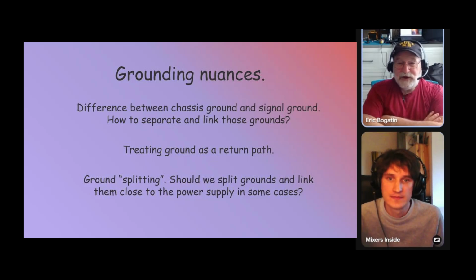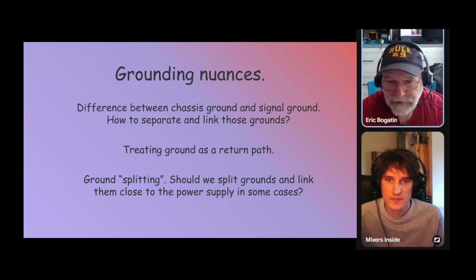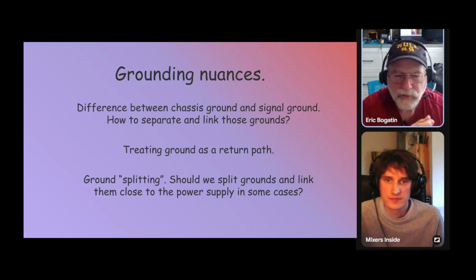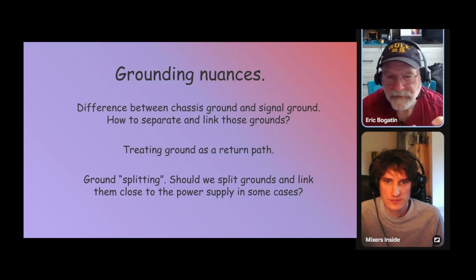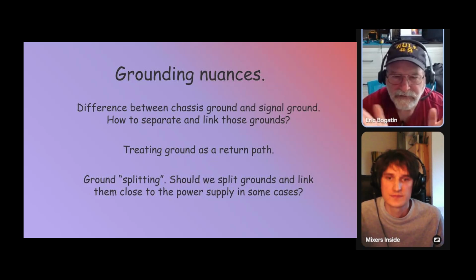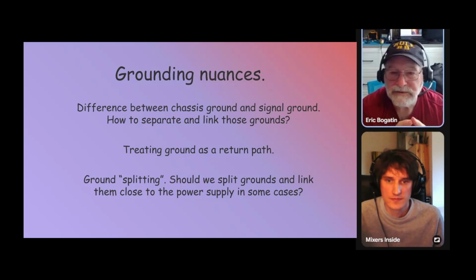The quick answer is no, because you still have the ground plane in the board that's still providing the low impedance for return currents, but you're using the separate trace as a reference. Typically with your amplifier, the preamp or the sensor or the microphone, the currents involved are really small. It's low level voltages, really small currents. And so the resistance of that trace is negligible. For 6 mil wide lines, it's about 80 milliohms per inch. So a couple inches long, we're still talking about a fraction of an ohm series resistance. So it's a negligible amount of resistance.